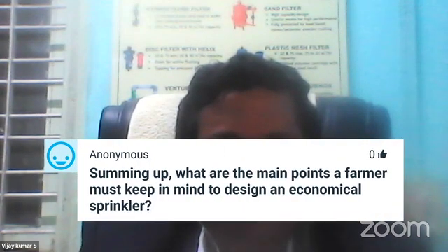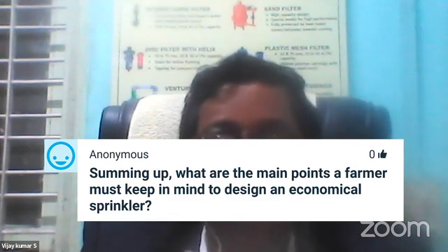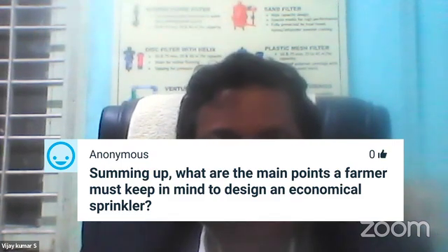And the next question is, summing up, what are the main points a farmer must keep in mind to design an economical sprinkler? In order to design a sprinkler irrigation system, first he should know the area that he wants to irrigate, and then he should know the soil type. That is very important. And you should select a sprinkler that is suitable to your land.